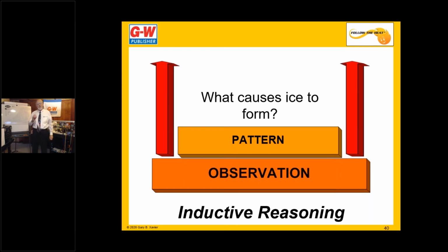So to get the saturation temperature below 32 degrees Fahrenheit, the pressure has to be lower than it should be. On an air conditioning evaporator, we never want an evaporator lower than usually 38 to 40 degrees Fahrenheit. On a refrigeration evaporator, sure, they run below freezing all the time.